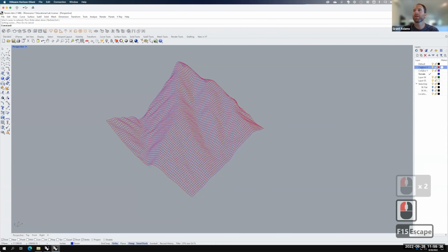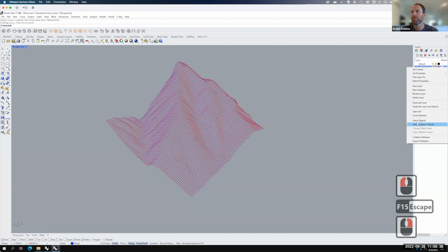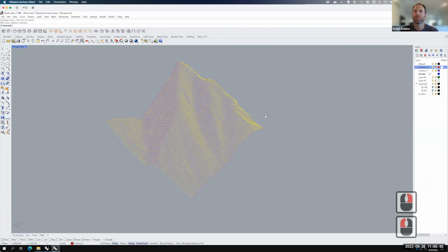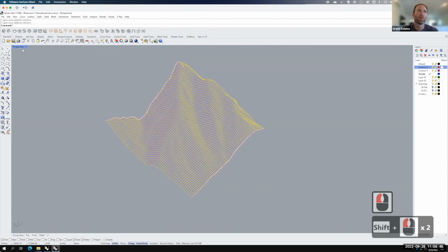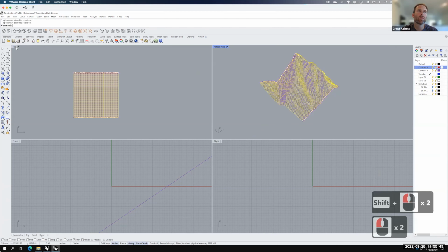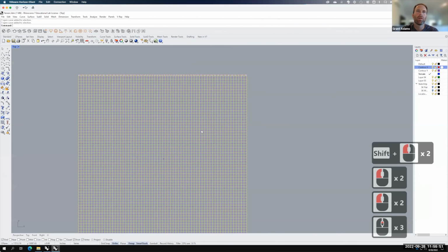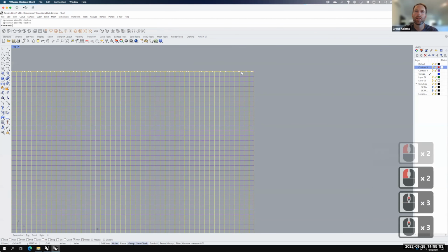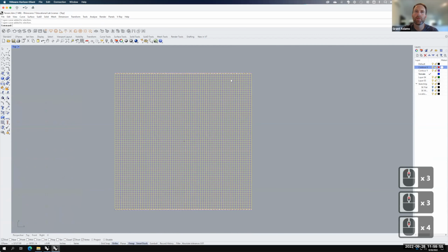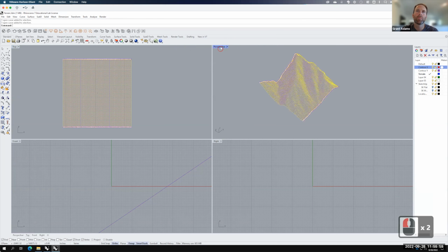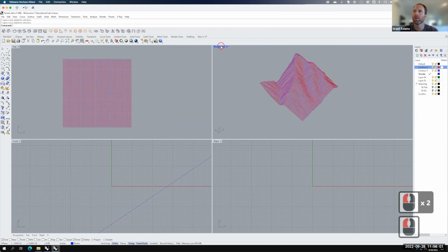So this time, because it didn't work, I'm going to select all of the objects in one direction. I've selected all of the contour X, and then we'll pick the 2 end curves like that and that. If we were looking at this in the top view, we would get all of the vertical curves and just the outside top and bottom. So that should allow us to work a little bit faster. Part of that is because when I'm doing it live, I don't want to wait.